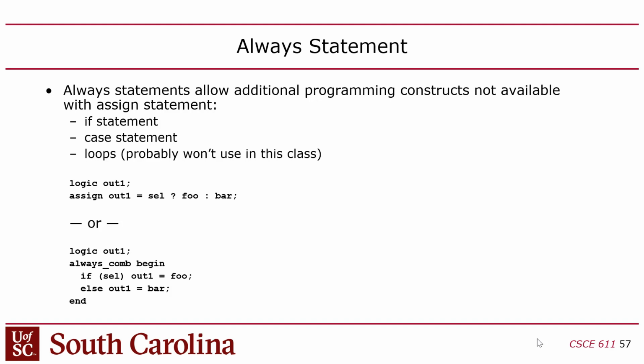Well, that's because what's happening here is that the always_comb is getting synthesized into a logic circuit, and it will activate whenever any signal that's treated like an input changes state. It will activate like an always statement. But when it activates, it executes the body of the always as an atomic operation, as a circuit, right? So even though you could think of an if statement as having sequential semantics, walking through one line at a time, the overall end-to-end behavior is combined into a digital logic circuit and it's activated whenever the inputs change.